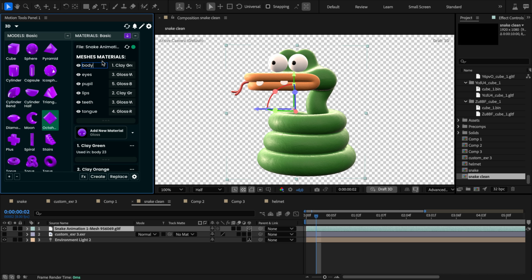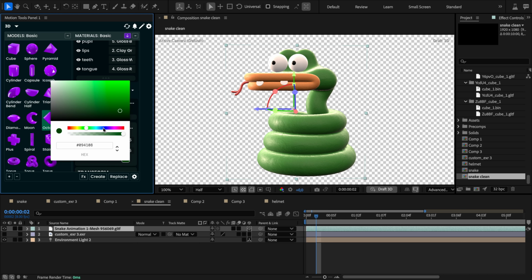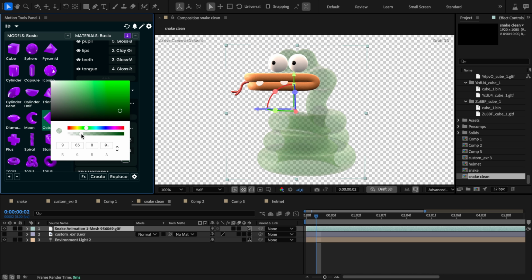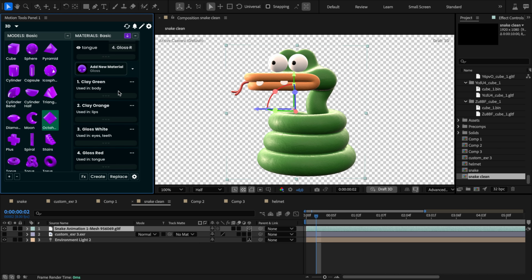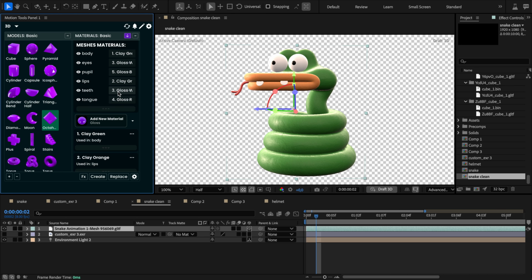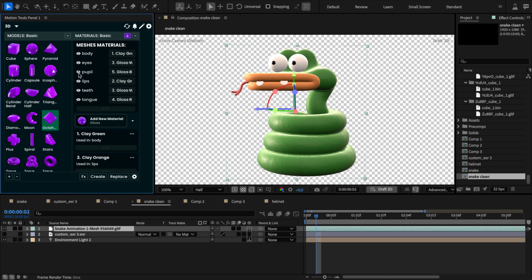Here's a cool tip. Base color in the PBR options doesn't just change the color. It can also control the material's alpha channel. This enables us to make the material and its linked meshes transparent. Best of all, it works from a single file. I use this feature to easily toggle the visibility of certain meshes from here by clicking the I button. So if your model consists of many meshes, you don't have to split the model into lots of separate files.